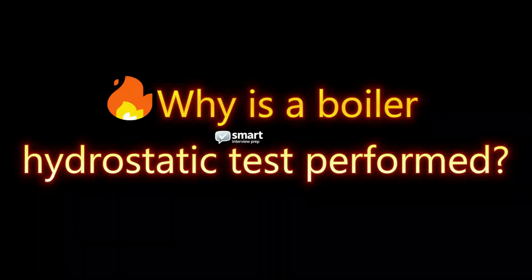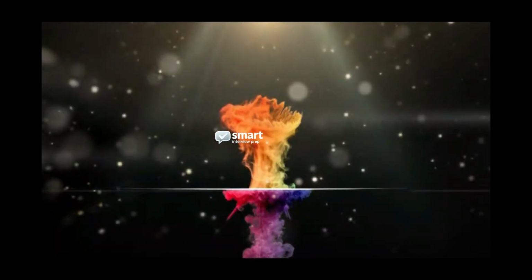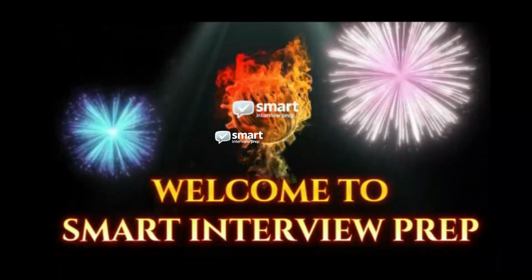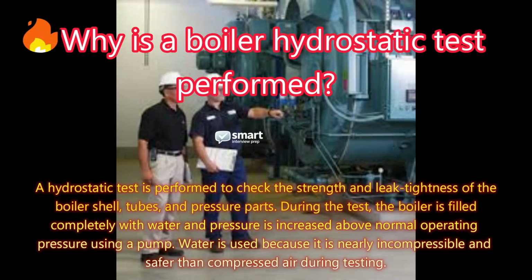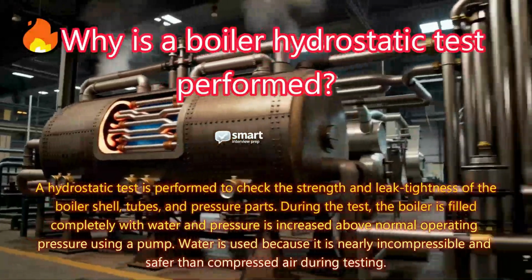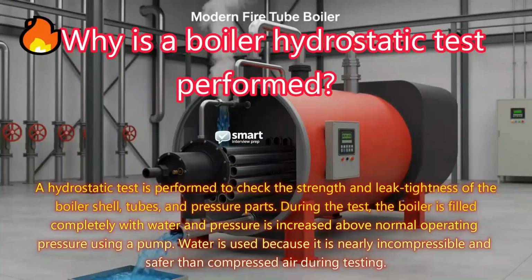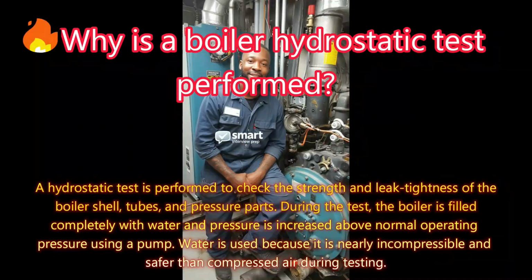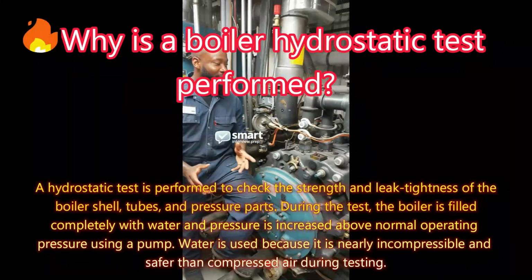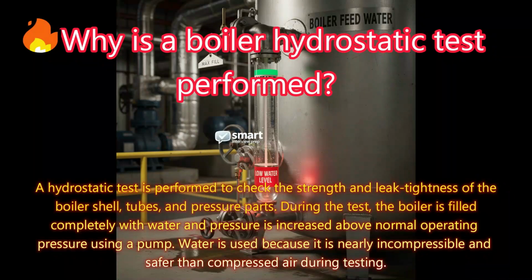Why is a boiler hydrostatic test performed? Answer: A hydrostatic test is performed to check the strength and leak tightness of the boiler shell, tubes, and pressure parts. During the test, the boiler is filled completely with water and pressure is increased above normal operating pressure using a pump. Water is used because it is nearly incompressible and safer than compressed air during testing.